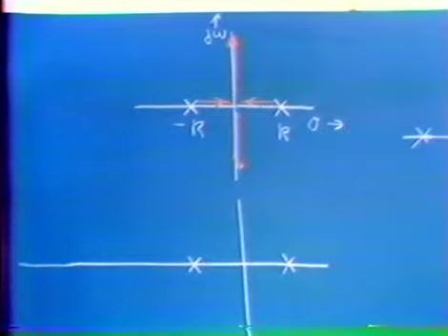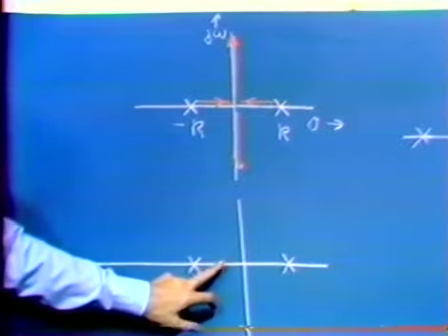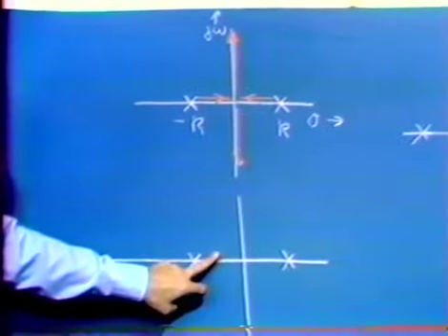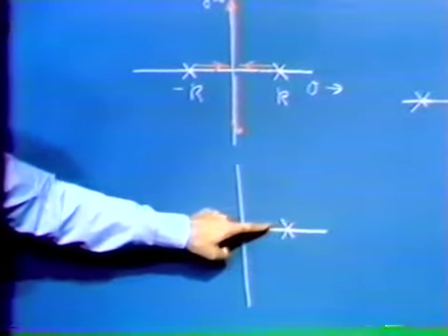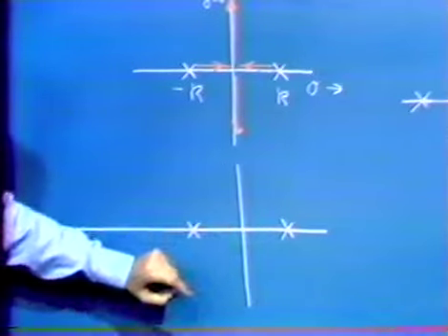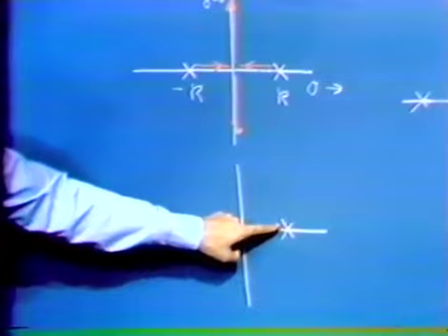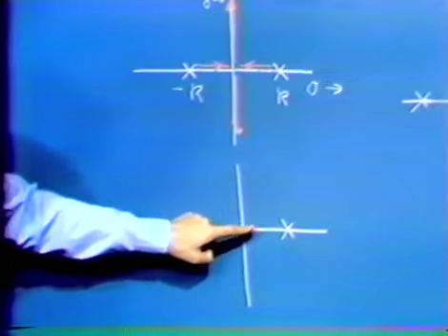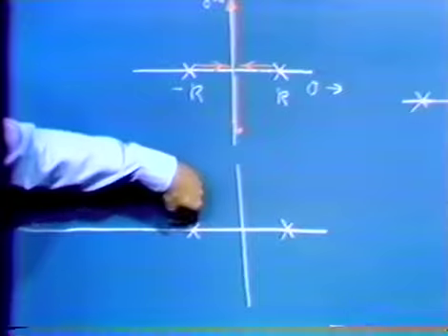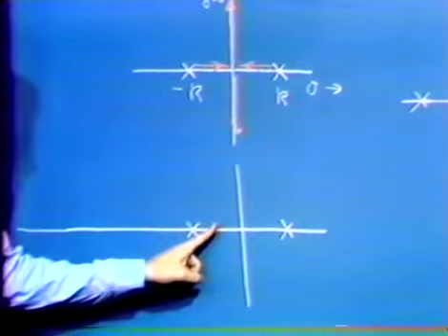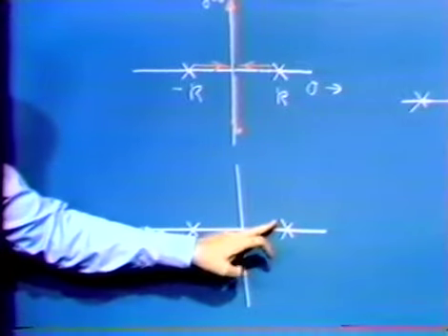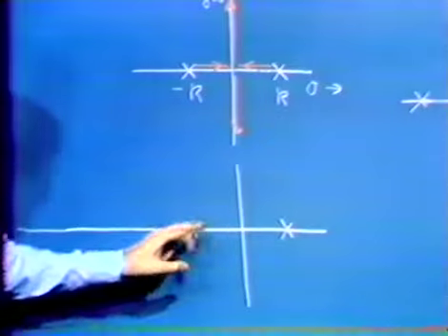putting a zero anywhere in the left half plane improves the performance of the system. For example, I could put a zero in here. We have to put it in the left half plane, but if I added a zero, for example, here, our root locus diagram would simply be such that this pole moved toward the zero. For sufficiently large values of A0, we get this branch in the left half plane. In the meantime, the branch starting at this pole would simply move left. So we could certainly, by adding a zero at this point, for some range of values of A, have both closed loop poles in the left half plane.